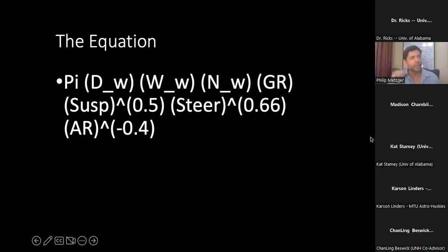Okay, we haven't tried to look at that, but we have seen teams use different approaches. It depends on your mining system. If you've got a load-haul-dump system, a front-end loader, where you use your wheels to drive that bucket forward through the dirt, then your mobility system is part of your mining system. And so you're generating the digging force with your wheels.